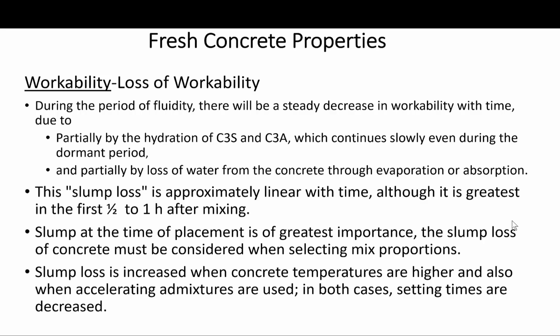This slump loss is approximately linear with time, although it is greatest in the first 30 minutes to about 1 hour after mixing. So since the slump at the time of placement is really of greatest importance, the slump loss of concrete must be considered when selecting mix proportions. So slump loss is increased when concrete temperatures are high and also when accelerating admixtures are used. In both cases, the setting times are decreased.